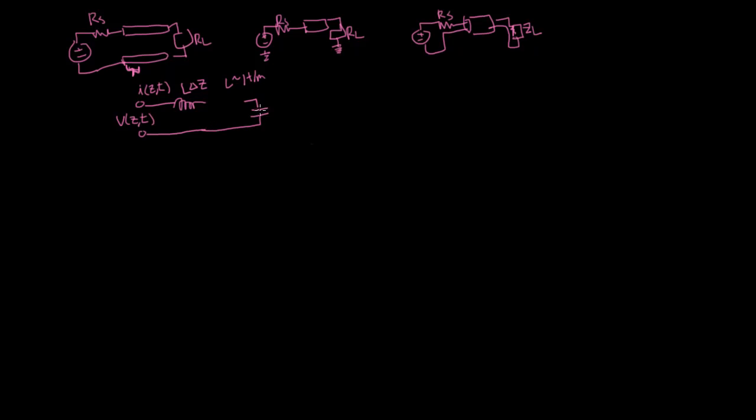What the shunt capacitor means, remember, a capacitor starts out as a short and then eventually becomes an open circuit. So that means the voltage won't really react immediately to whatever's going on back here. We show that through a shunt capacitor, which again is in units of capacitance per length. So remember that this capacitance is actually in units of Farads per meter, not just Farads. So you have to multiply it by the unit length in order for it to be capacitance in the traditional sense.